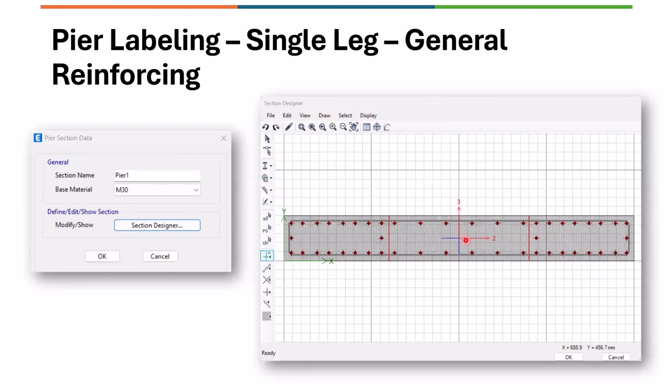Your program will assume by default a ratio of about 0.2 or 0.3 percent, the very minimum one, and then the iterations or interpolation within the design cycle will happen, and it will report the required area of vertical reinforcement, right?